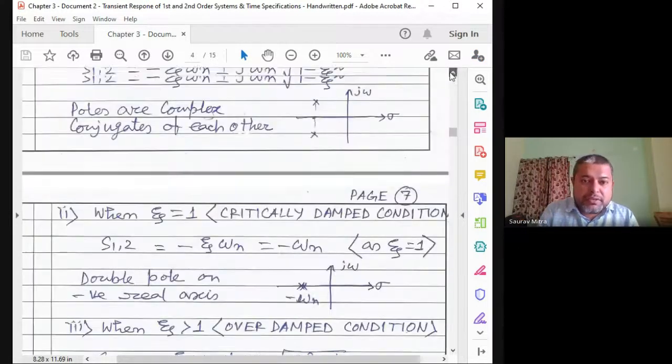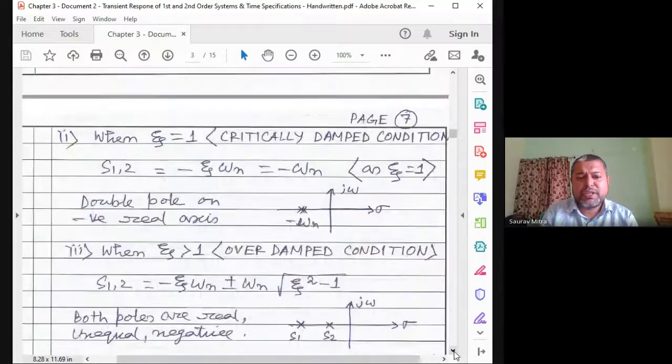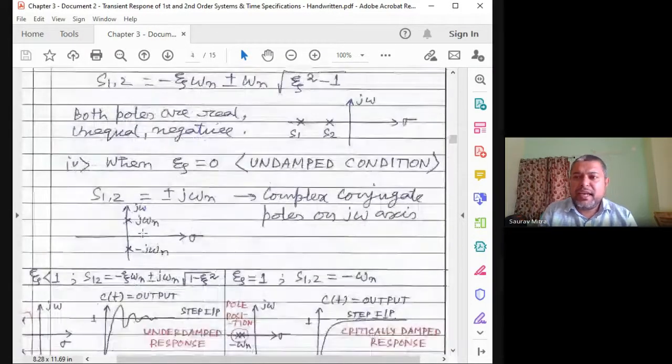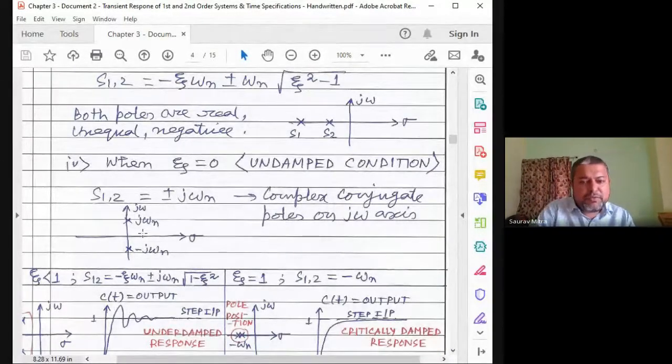So there you should not get scared or anything. First, this is the characteristic equation, this is the roots, take minus 1 common, this is the pole equation for the second order case. Now keep on doing the cases. If you are doing the cases, the first case is zeta equal to 0. In that case, you will find both the roots are coming on the j omega axis. And I have given you this pole position, I think plus minus 2j.